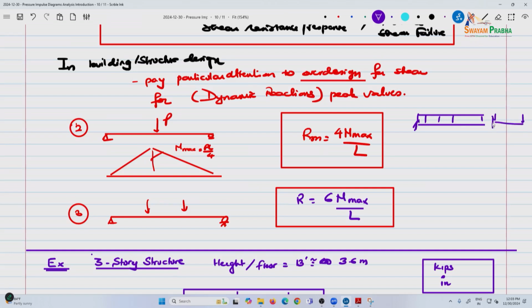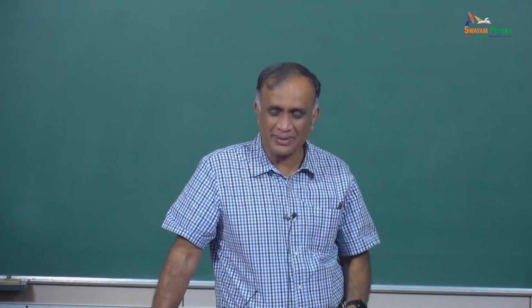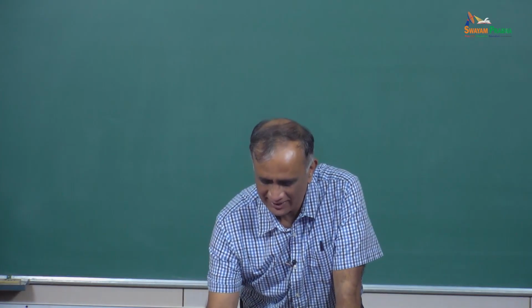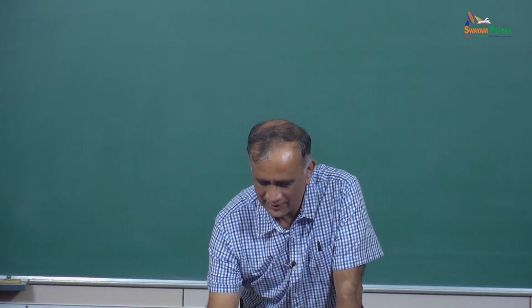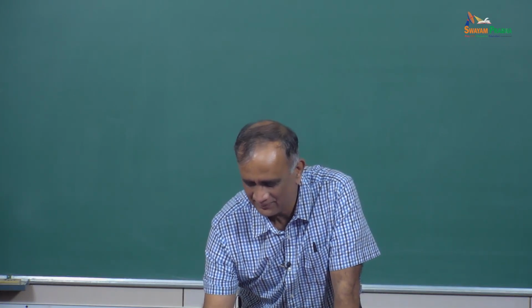What's your Rm going to be? Anybody? In terms of Mmax. Two Mmax by L, right? So what's your moment here? wL square by 2.